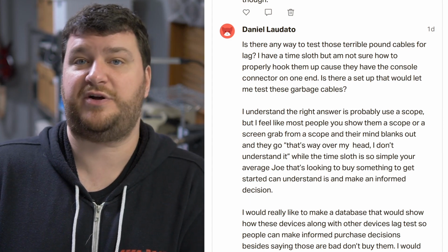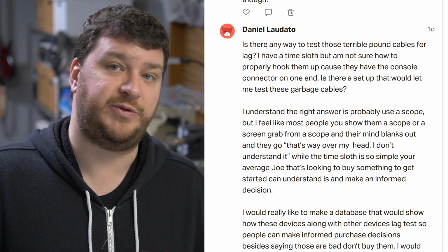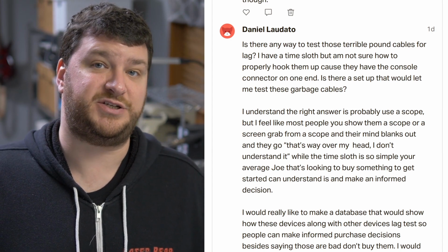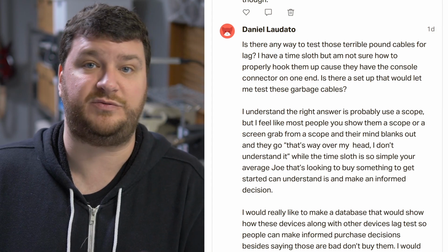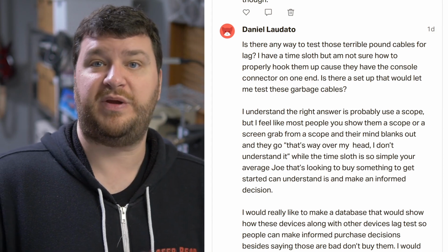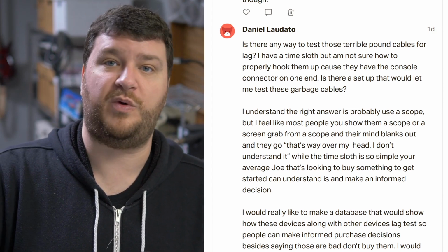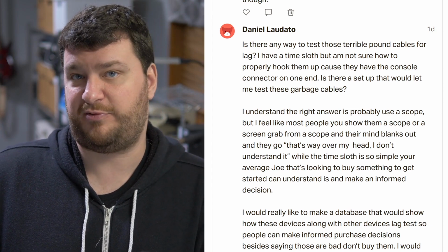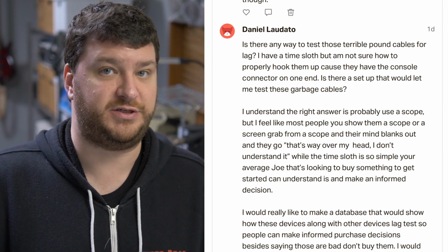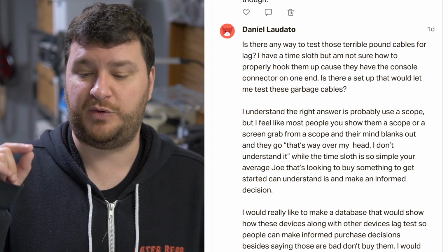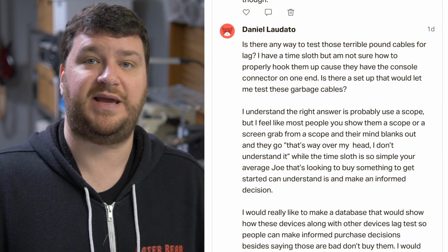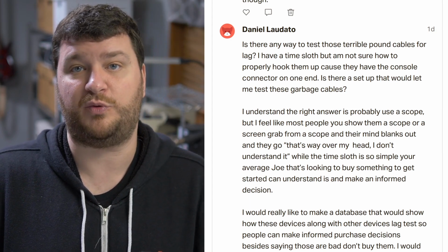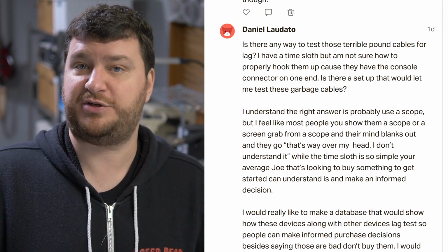Now, this could be an Extron device. This could be a passive device like I built in the video. Or you could even probably use an HD15 to SCART to get it to a SCART connector and then make yourself a breakout. But at that point, whenever you get C-sync, meaning composite sync, not separated sync, at the right voltage, then I would solder it to both the composite and the C-sync outputs. You're not pulling both at the same time. The cable will either pull one or the other, and then make sure RGB is connected.